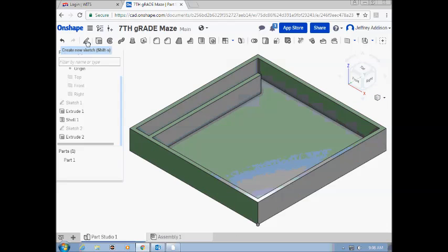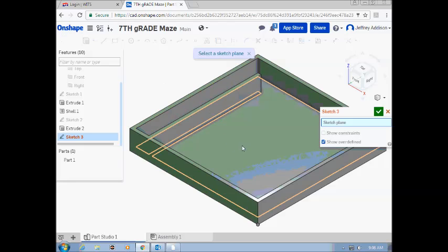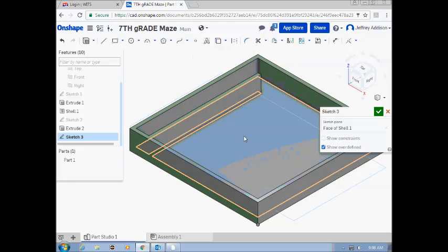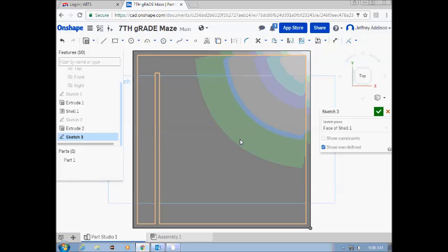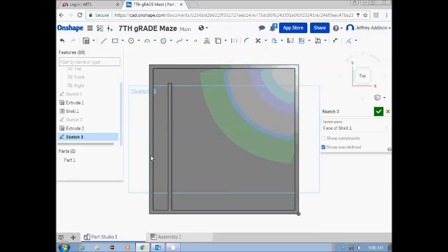Back to the ISO. We're going to draw on this, just to have a start of a maze. What we need is a place for our BBs, the balls that are going to be going around inside the maze, to rest, so we're going to create some holes here. We're going to use this circle tool, go inside this hallway, and make this hole a diameter of 0.1.